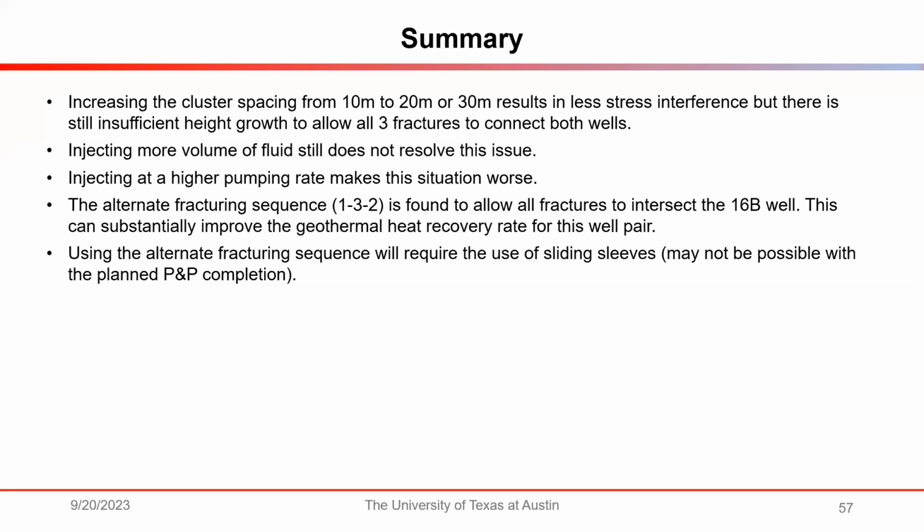So we actually compute where you have dilation and shear failure events, and wherever these events are, the magnitude of the slip, the displacement of those events, allows us to compute the moment magnitude, and the orientation of those events allows us to calculate the moment tensor. So it just depends on what the displacement is at any particular displacement discontinuity. And if there is displacement there, then it'll generate a microseismic event and we can compute that.